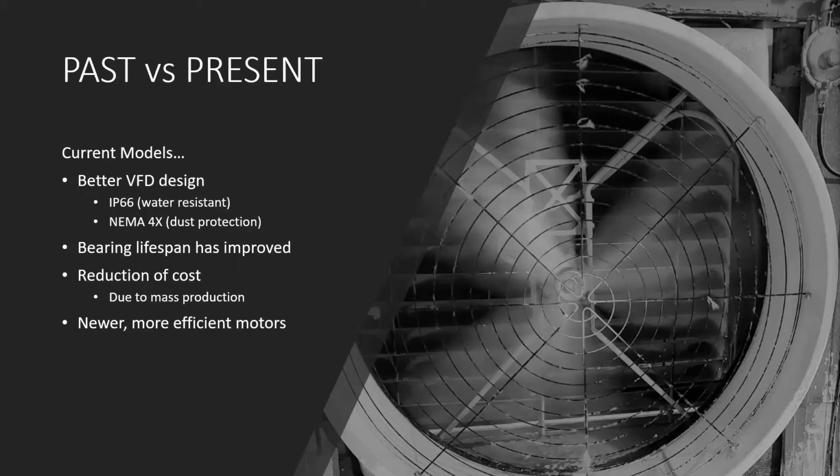Now, to look at your current variable speed options, which is what our Valco VFan is, we have a better variable frequency drive available on the market nowadays. What I mean by that is that as far as washing the fan goes in between flocks, you don't want to have to worry about water splashing up on the VFD control, which in this case, the one that we use is water resistant, so you don't have to worry about that.